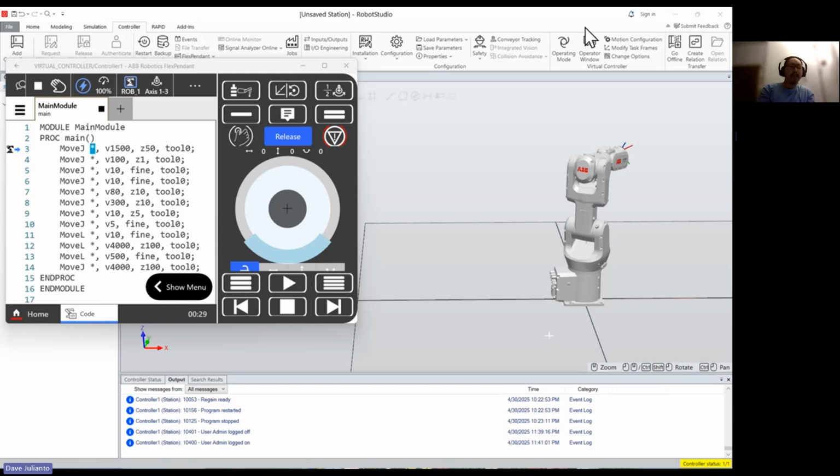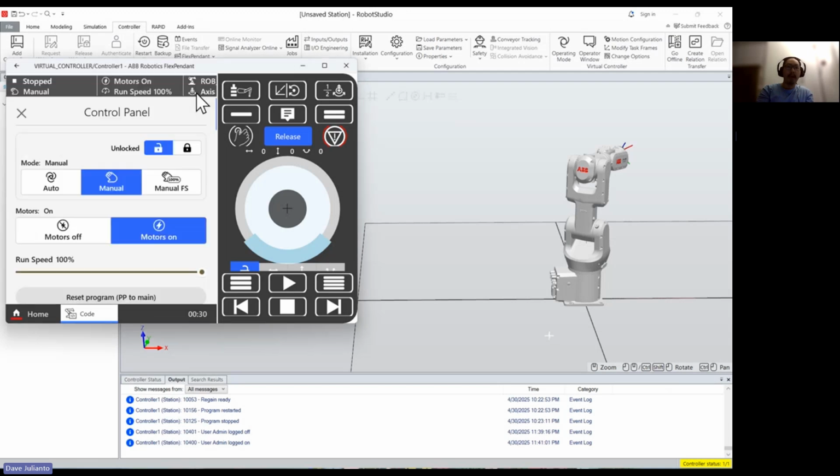So I am from Team 24, and we were tasked to program robot moves using ABB Robot Studio software for the project. So before we start, we must make sure that the controller is connected. And for this project, we are using Flex Pendant. And this is not connected to the robot yet, but make sure that the motor on this Flex Pendant is on.